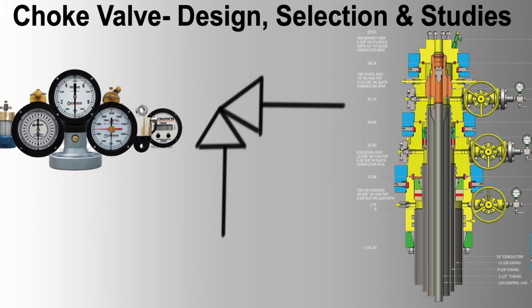Advantages: precision, provides precise control over flow rates using replaceable orifices. Simplicity, simple to operate and maintain. Cost-effective, lower cost compared to adjustable choke valves. Disadvantages: manual adjustment, requires manual replacement of orifices to change flow rates. Operational downtime, changing orifices can cause downtime and interrupt operations.